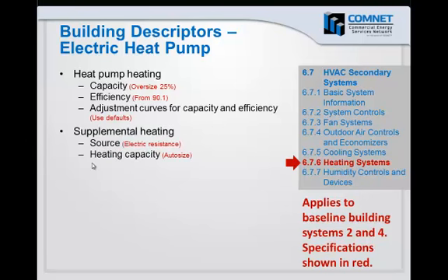There's building descriptors dealing with supplemental heating, which would come on when temperatures drop and the heat pump itself is not capable of meeting load. The source for supplemental heating in the baseline building is electric resistance, and its capacity is auto-sized.